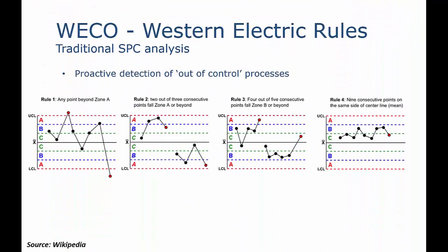Going further, in SPC you have rules such as the Western Electric rules for proactive detection of issues. Put simply, it defines alarms for out-of-control processes and originated back in the 1950s. One problem here is the dynamics of manufacturing itself, as we looked at, and your ability to understand the relevance of received alarms. Another is that on average, you'll receive one false alarm per 91.75 observations.